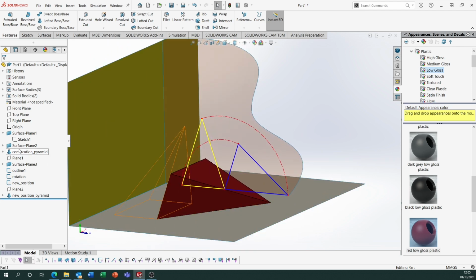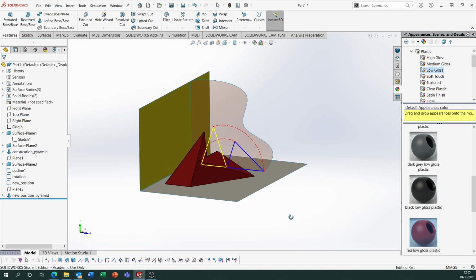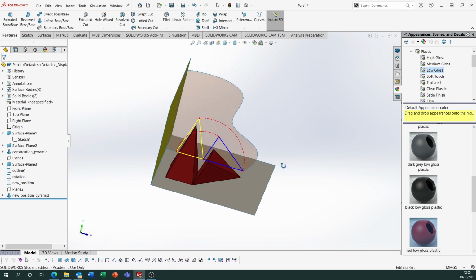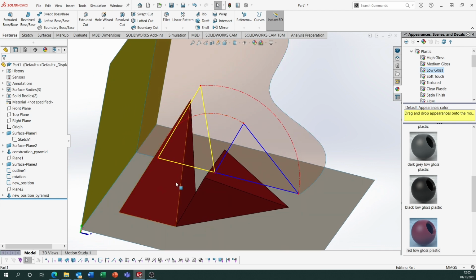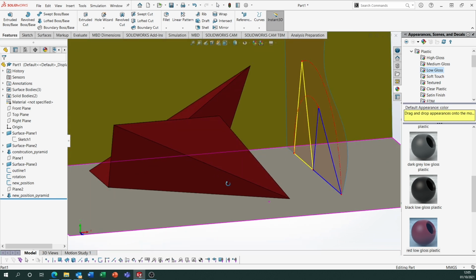Okay, or you could show both. It's up to yourselves how you do it. Okay, make sure to label vertical plane, horizontal plane, your traces, label different points. So you could label points 1, 2, and 3, and then show them rotated around here. So it might be 2A and 3A when you rotate them into their new position.